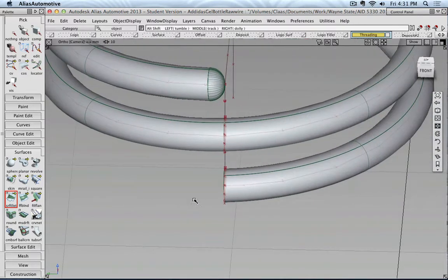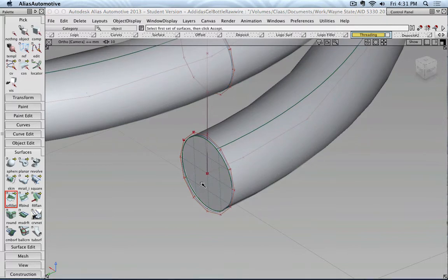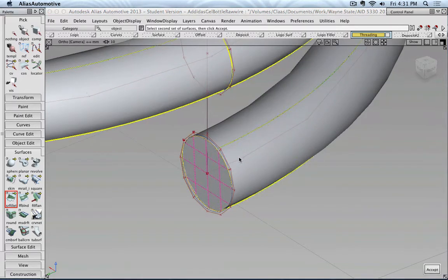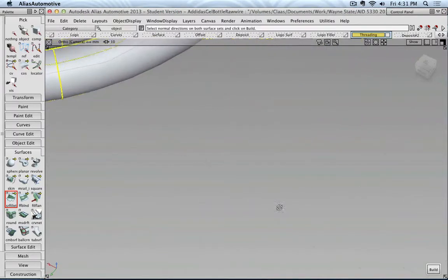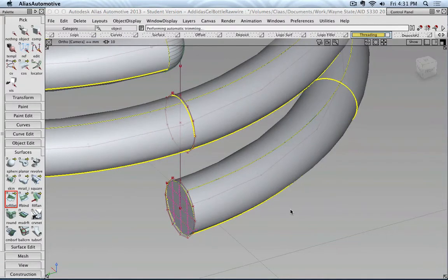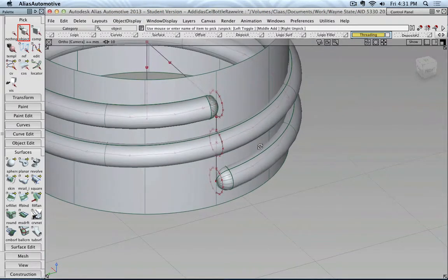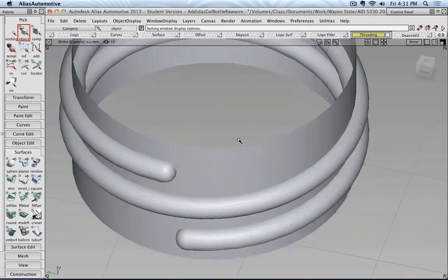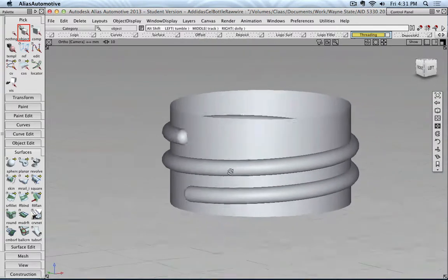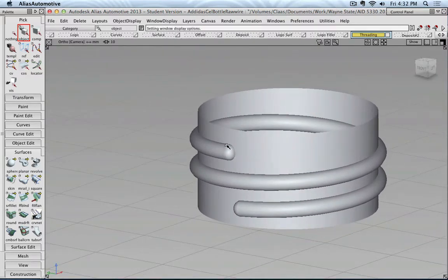So we can, with that fillet value still inside the tool, go to the lower part and then select the other two parts. Okay, the vectors are correct. And there we are. Perfect. Okay, then we can show everything again. Let's turn maybe the wireframe off for a moment. There you can see that it is of course not necessarily the way most threadings will look like, but a rounded edge still looks much better than, for example, a sharp edge.